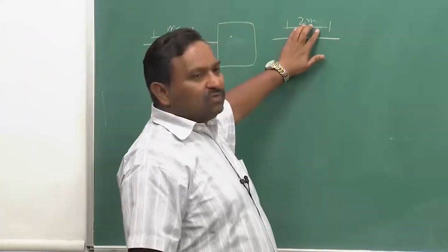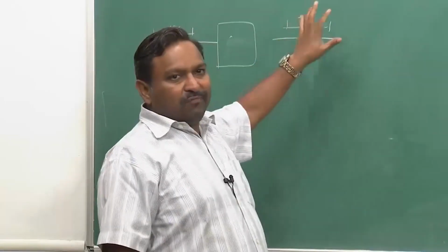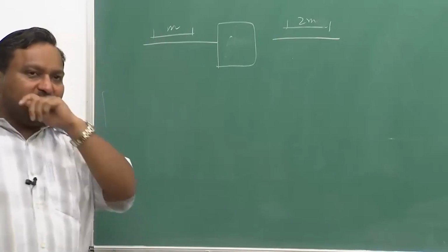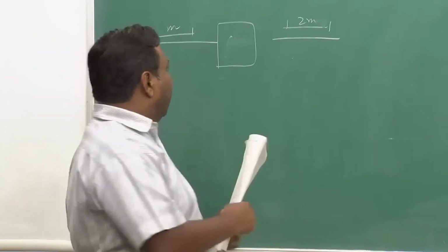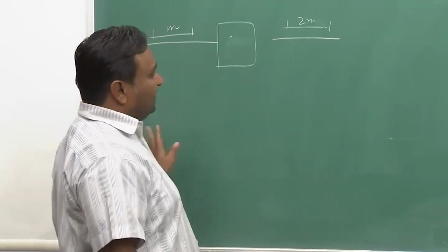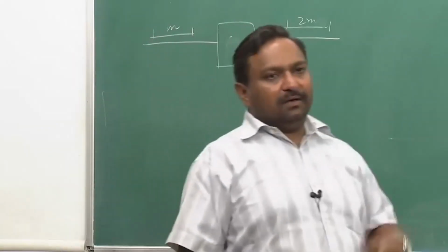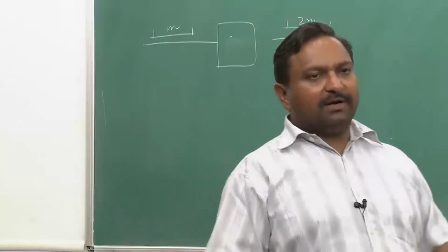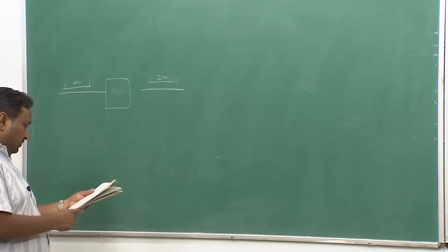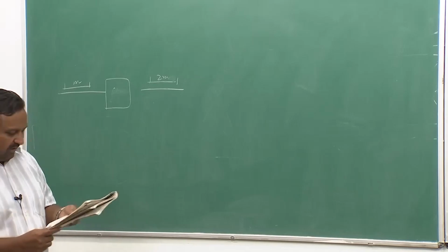So there will be 2M minus 1 slots in the 125 microsecond frame and there will be M slots in the 125 microsecond frame, and the clock will be derived from the input, and I will actually do the doubling, a doubler, to create a double rate clock for the reading operation. So we will be using 2 RAMs here. So let us build up the structure.